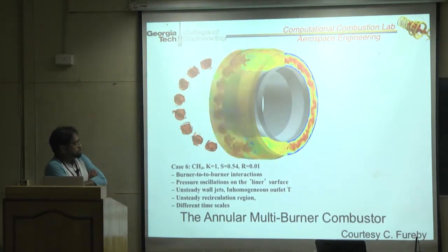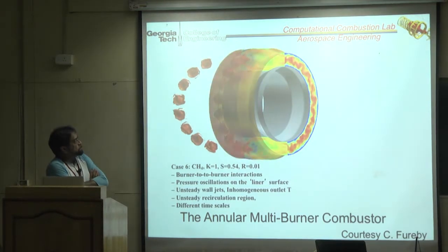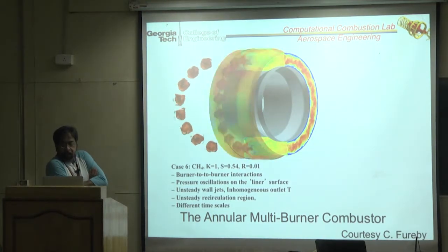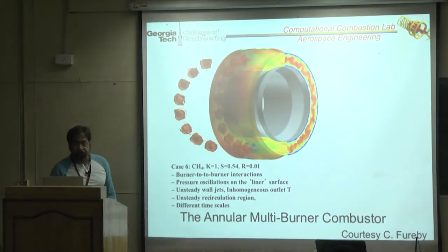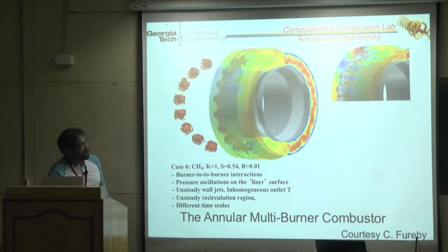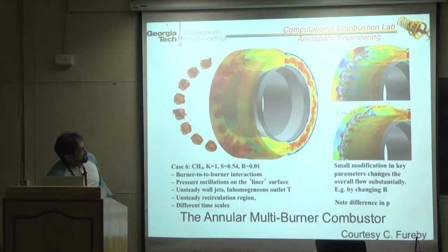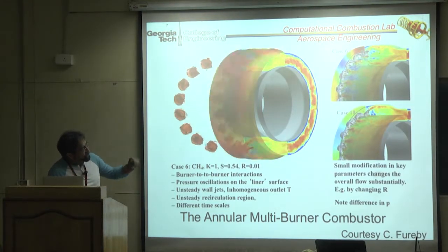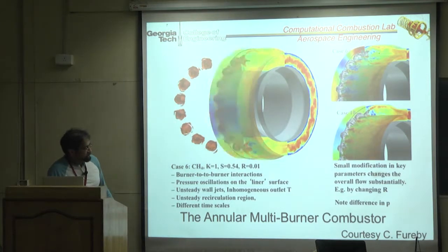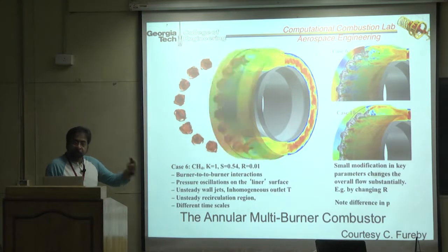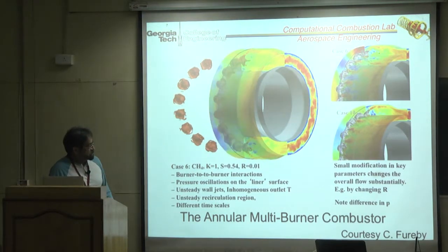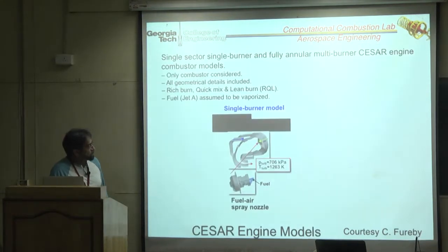It's expensive, and usually there's not much data in it. But on the other hand, if you just took one burner and looked at it, it doesn't seem to have the physics. Small modifications make big differences to the changes in pressure drop, which is why multi-burners can easily get into transverse instability, and I'll show you an example again.